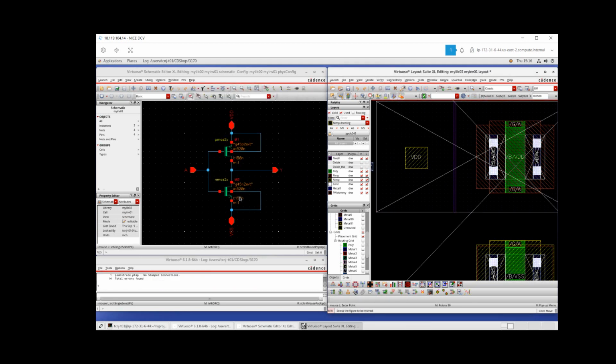All right, so I don't see any markers between this P implant and N implant, and also I don't see any markers on the side. So I'm happy with that connection. The only question is on the size of this edge of the P well, whether it is too far. Certainly it's too close to the metal, so I have to do something about that. But I may be able to move it back a little bit.